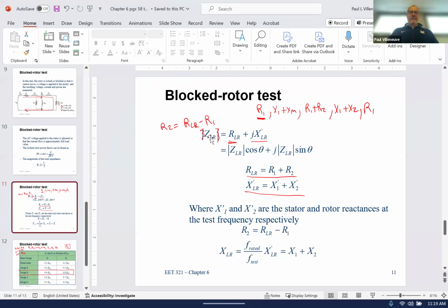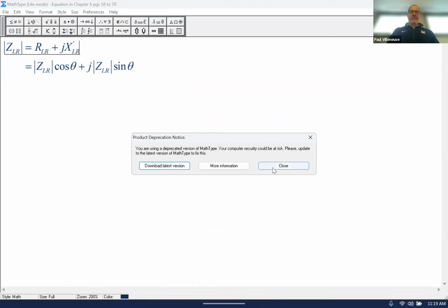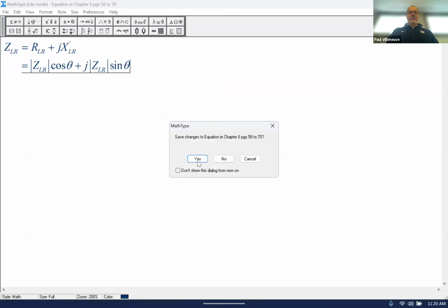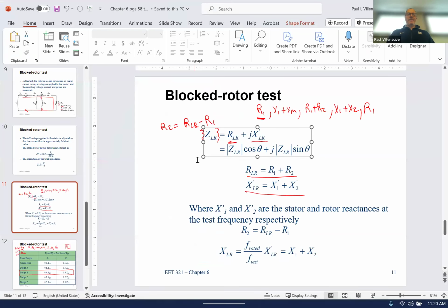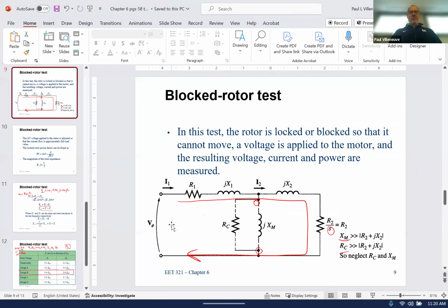How do you measure those? Does it show in the slide before? Measure what? Like how you find the Z from? V divided by I. Okay, so you're measuring your V. All these tests, right? If I'm going to do block rotor tests, I apply voltage. I measure the current, but that voltage has to be across all three phases because I want that to be under normal operating conditions.